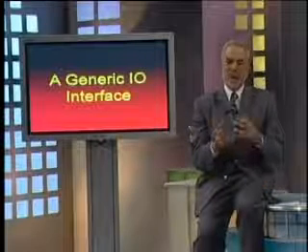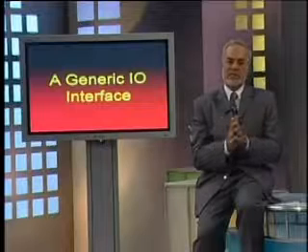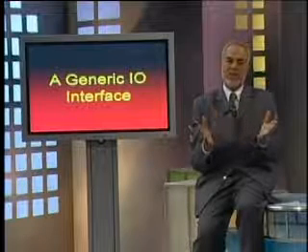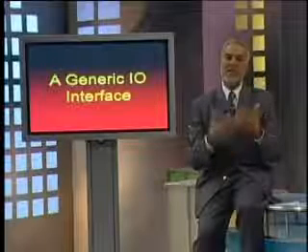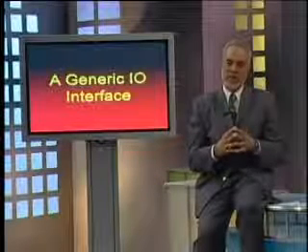So using partly some lines from the address bus and some from the control bus, the decoder would generate the enable signal or the corresponding clock signals.